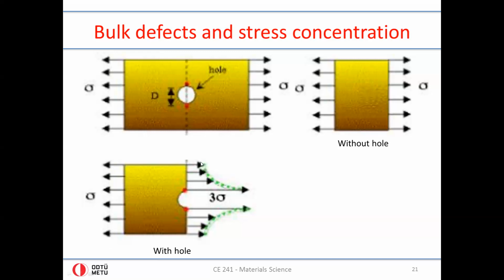So the pressure distribution or the force distribution or the unhappiness distribution along this portion of the plate, the middle of the plate, is uneven. And it's uneven in the sense that the most unhappiness is felt here. So you might imagine that if you keep pulling on the left and on the right, the very first portion of the plate to break will be this point and this point.